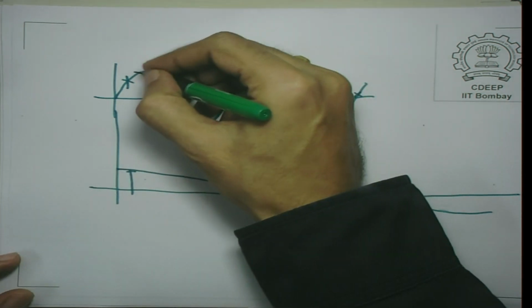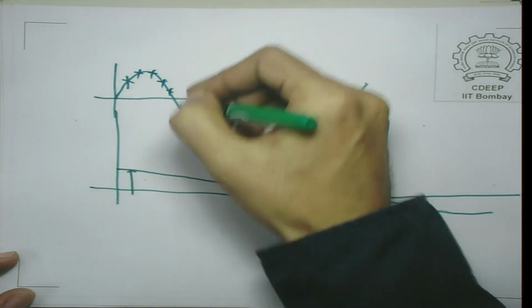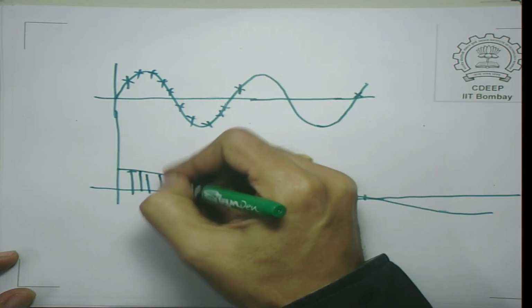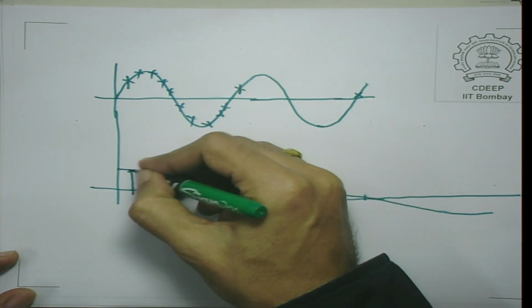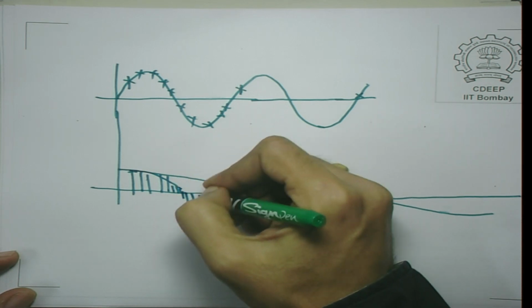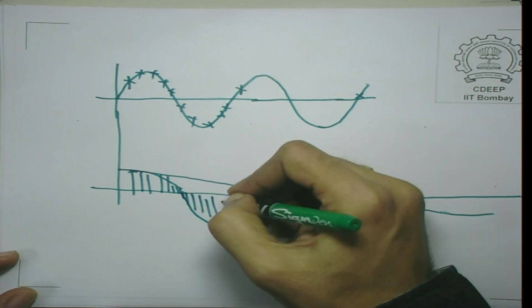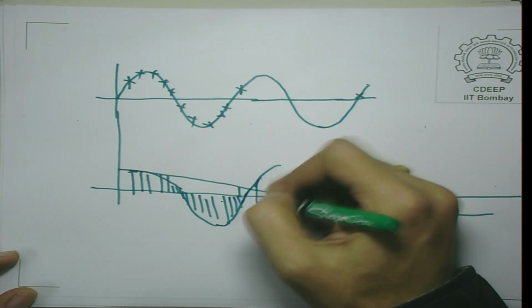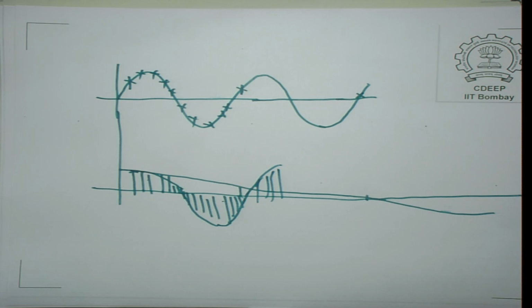What you of course need to do is take a lot of samples, which is related to the frequency of the wave which you are trying to measure. If you do that, then you will get the correct inference if you interpolate and so on. Okay. So, if you choose a sampling frequency which is very low, you will actually see an effect called aliasing.